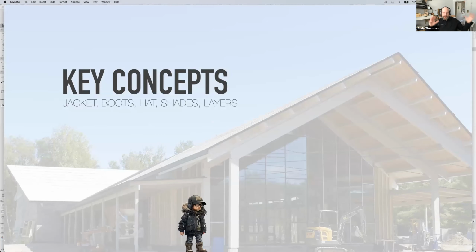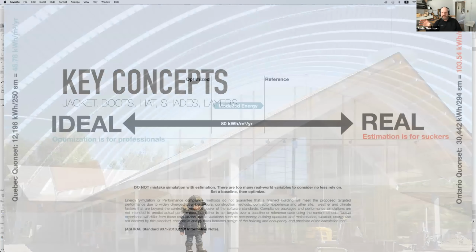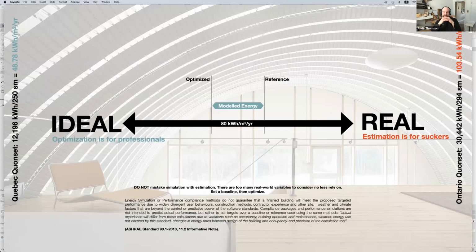So if you think about this little figure, this is the person or the building with that shade protecting layer to limit summer gains. This is the wedding facility we did in Innisfil, just south of here. So we've got these verandas that limit solar gains in the summer, but permit all of the gains in the winter. So we're basically building a solar oven to bring in as much heat and light as possible in the wintertime, but then block it entirely in the summer. And we've done a whole series of these buildings where we've kind of been experimenting with minimizing the surface area of the building, making it thermally really efficient because we've got the large volume, but the small surface area.